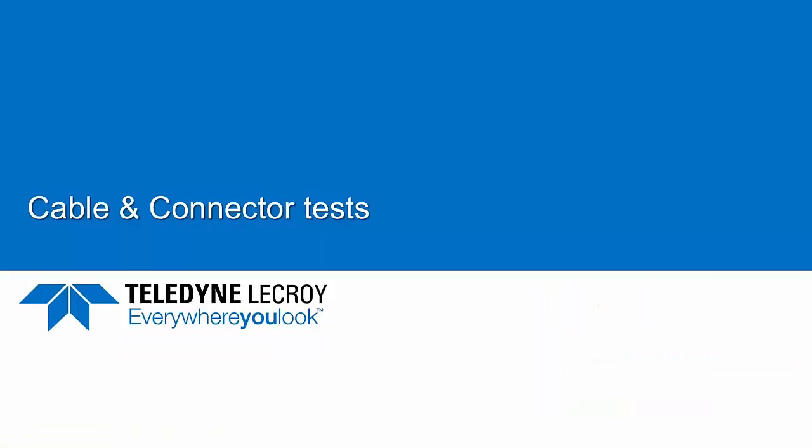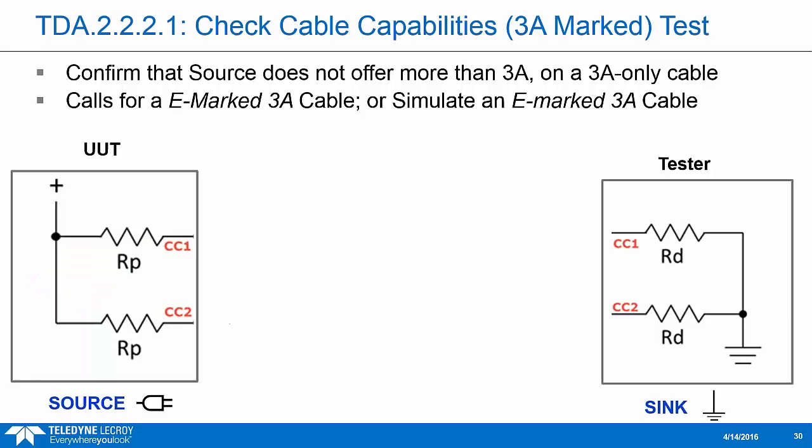Okay, cables and connectors. There are a handful of tests here specifically for cable markers, and they're all pretty simple, nothing too tricky. But one of the more critical tests for safety is TDA 2221, check cable capabilities. Looks like a cable test, right? But it's actually for PD devices. We want to verify that a source doesn't offer more than 3 amps on a 3 amp limited cable.